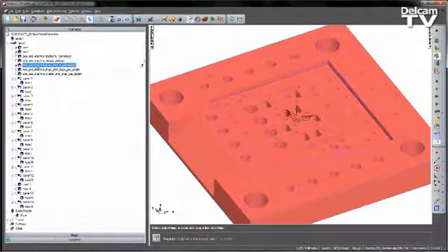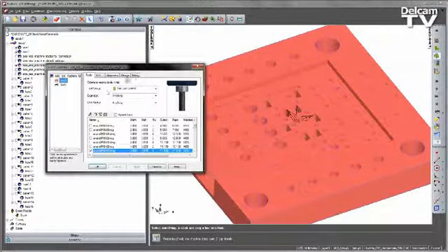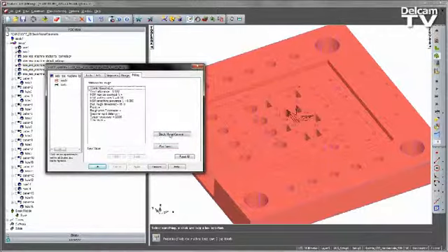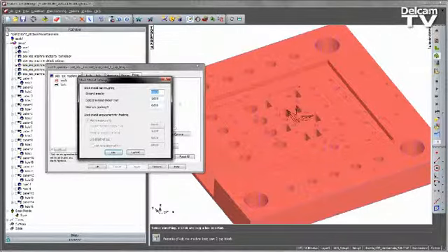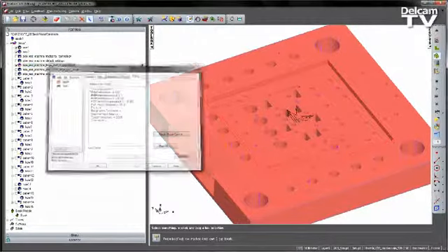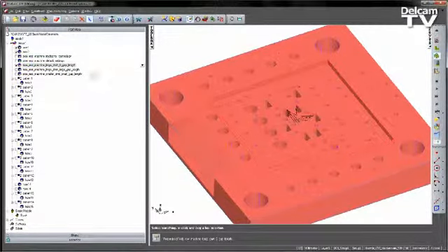So the next operation, which is the side rest machining, this time if we go into the roughing, into the milling area, into the stop model options. In this case we've set a 0 gap length, we've got 0 expansion, but we've set detect material thicker than to 1 mm. Now this is a common mistake, to set the detect material thicker than value to whatever the status of the previous roughing or machining operations was.